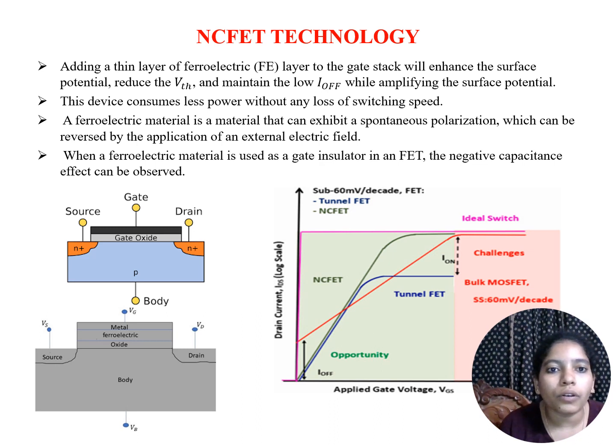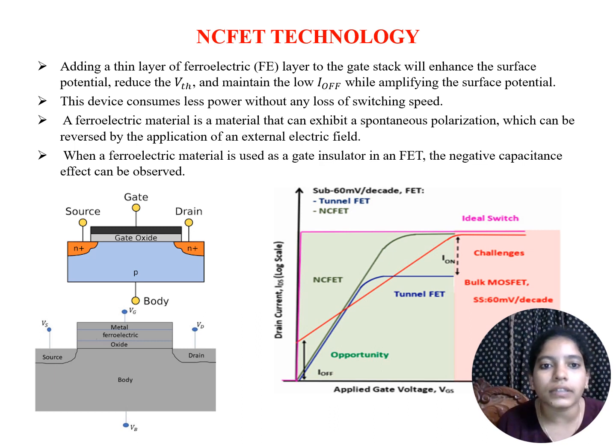Now, due to the low on current in TFET, we move to the next technology, NCFET technology. NCFET is nothing but adding a thin ferroelectric layer to the gate stack, which will enhance the surface potential, reduce the threshold voltage, and maintain the low off current while amplifying the surface potential. A ferroelectric material is a material that can exhibit a spontaneous polarization, which can be reversed by the application of an external electric field. This device consumes less power without any loss of switching speed.